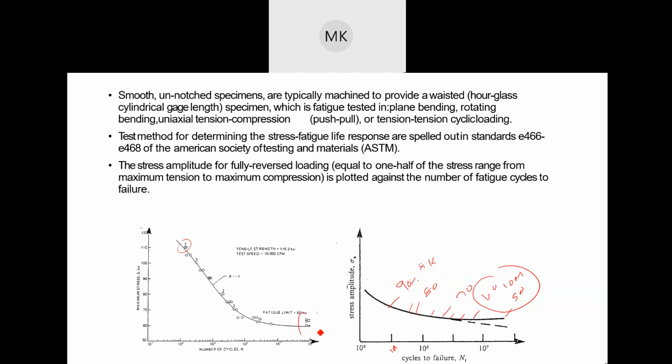and therefore these are the reasons why. If you see anything in a fatigue curve that has an arrow mark next to it, that means that sample didn't fail, and that is at 10 power 7 cycles mostly. That's when they stop it. And so you have flattening that is happening, and then you know that that's the point at which 60 ksi is your endurance limit for that material.